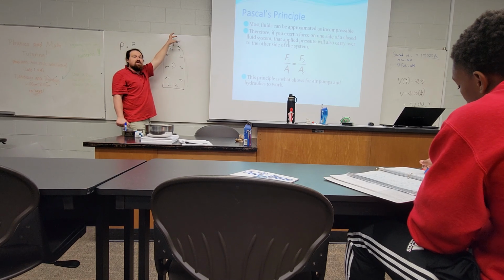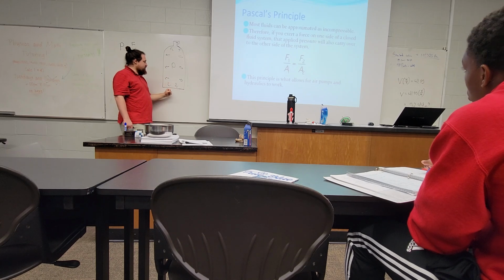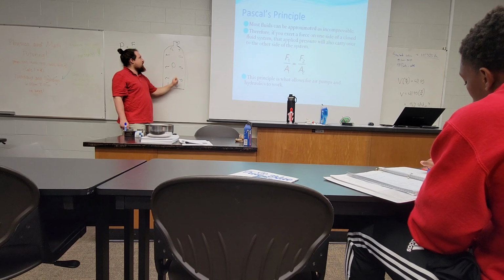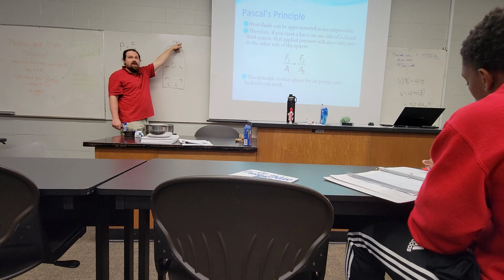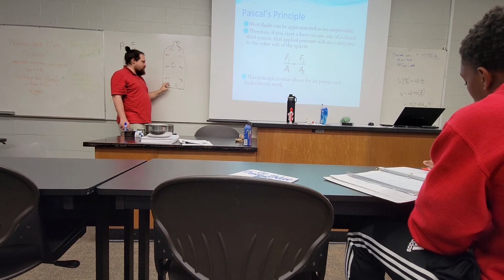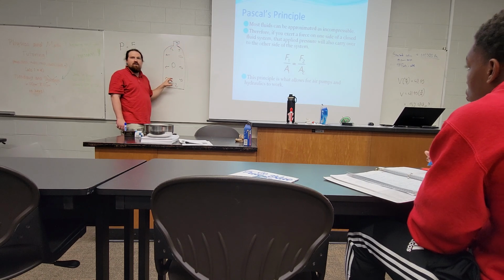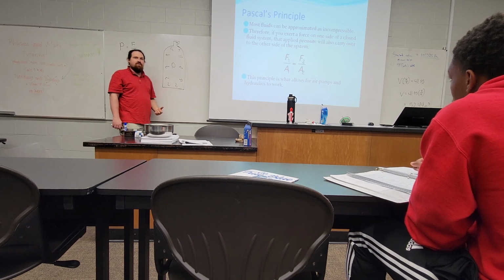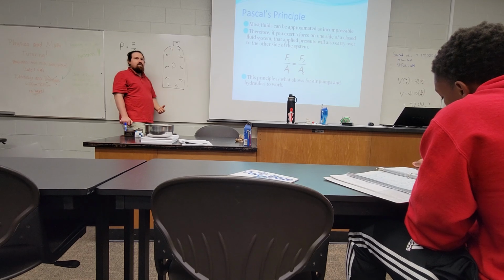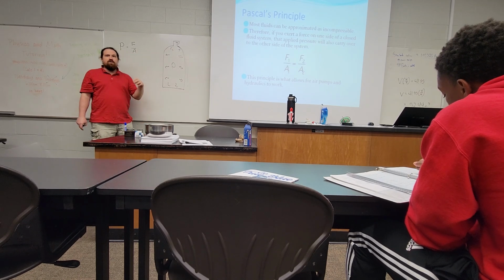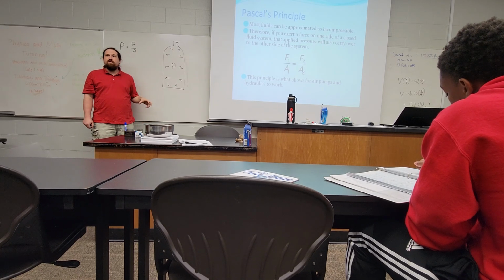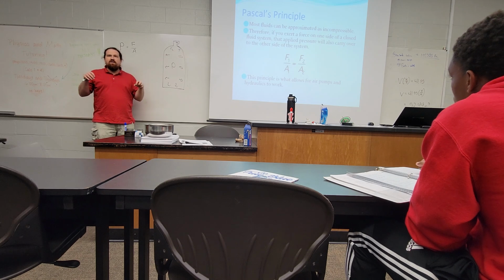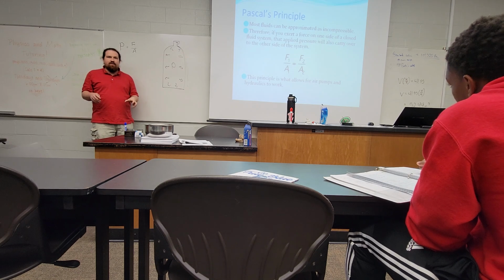And as a result, the same pressure applies more force to the bottom than to the flat parts of this valve. And that's usually why the metal at the bottom has to be a lot thicker, to account for that increase in force. So the same pressurized system can exert different forces on different parts of the system based on the applied surface area of that part of the system.